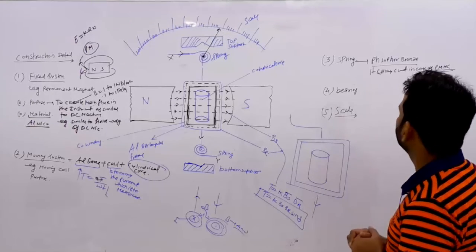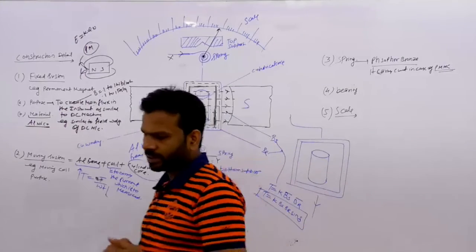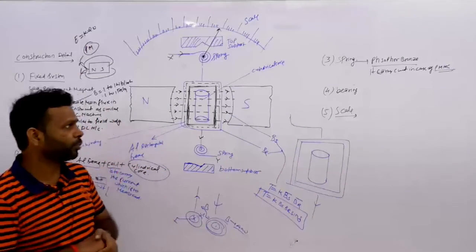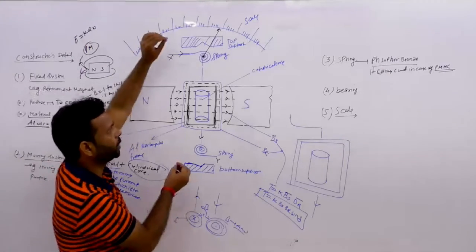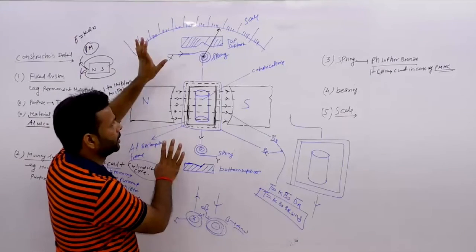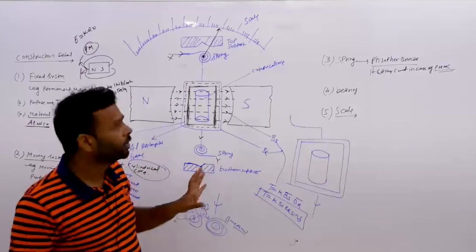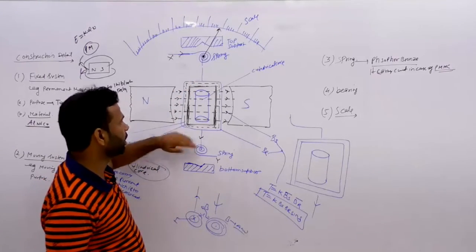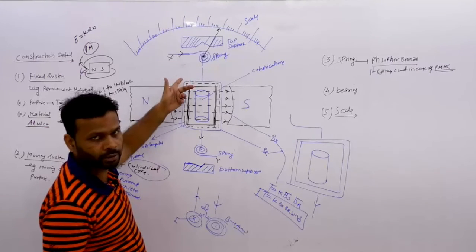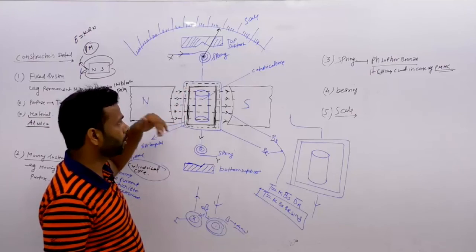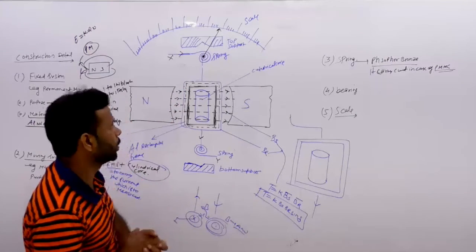And the next one is what? Spring. In case of a PMMC instrument, we will use constantan or phosphor bronze, and that is called a spiral spring. Its quantity is 2. In case of your PMMC instrument, the spring is carrying current, but in case of moving iron, they don't carry current. So in case of a PMMC instrument, if the spring breaks, then there is no deflecting torque, there is no reading. But in case of an MI instrument, if the spring breaks, then you can have something.